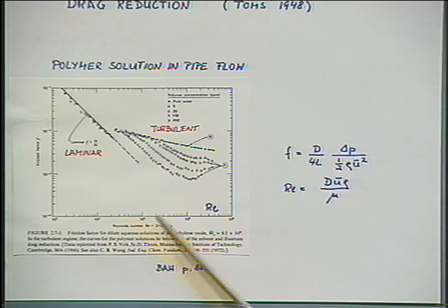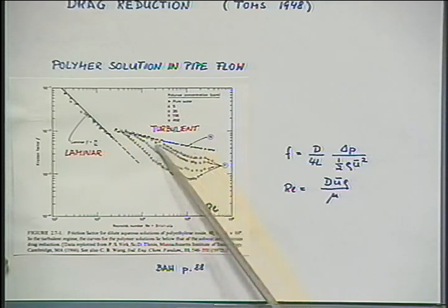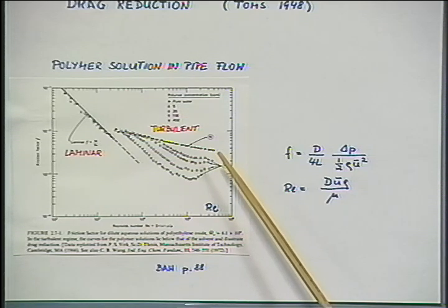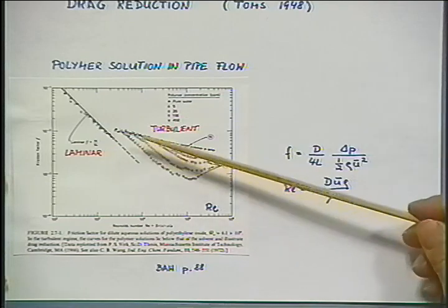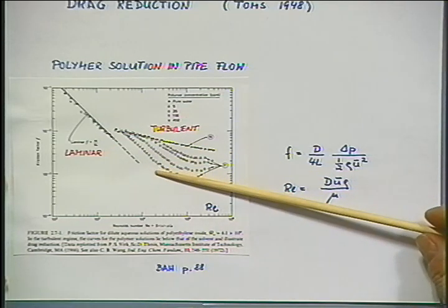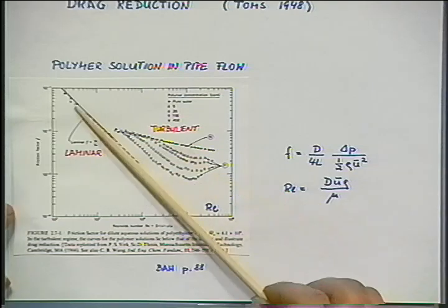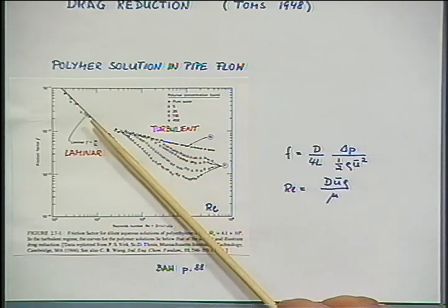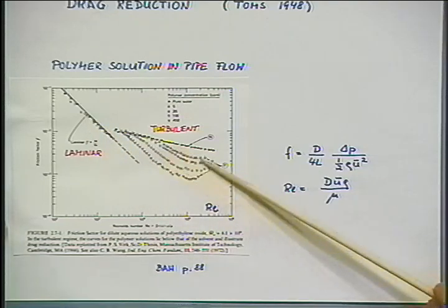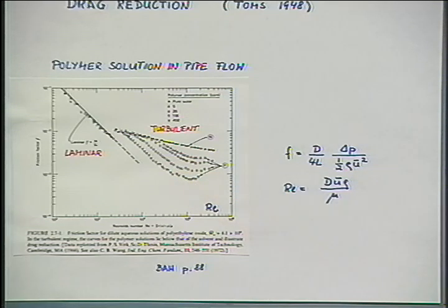However, when the flow rate is increased, when you go to higher rates, the flow becomes turbulent, classical fluid mechanics. So you know about that. But somehow the turbulence is changed when having macromolecules added. There are only few macromolecules added. The laminar flow is not changed. Viscosity is not changed noticeably. But certainly the turbulent flow is changed in the sense that it needs less energy for that turbulent flow. And then viscous dissipation is reduced. And in case of Columbus' ships, they just could go faster with the same power coming from their sails.